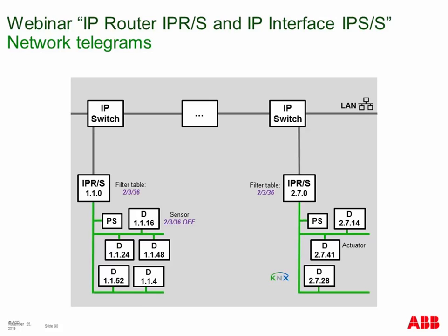Some more words a little bit about diagnostics. So we have several lines here. You see maybe line 110 and here we have line 170. We have a sensor in this line which sends the group address 2336. We press the rocker.